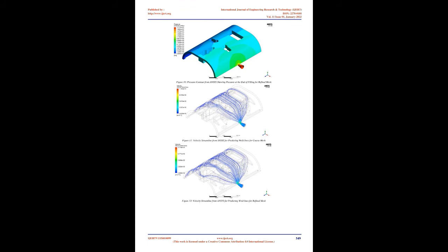Table 2 is a ranking matrix to determine the optimal gate location. In the ranking matrix, numbers 1 to 4 represent the rank of a particular gate location in a specific result, with 4 being the best and 1 the least. Table 2, Injection location ranking matrix. The selected results for comparison were those related to productivity and defects of concern such as short shot and structural integrity, hence they can be considered to be of equal importance, therefore not requiring some form of weighting. As observed from the ranking matrix, the inner center gate and the outer center gate are the highest ranking positions with a sum of 18 each.